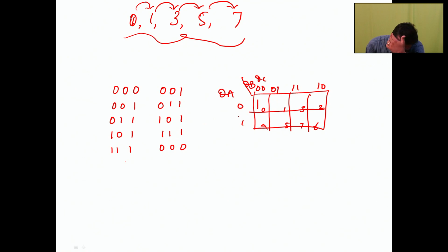They have given these outputs. For all the other conditions they have not given anything, so 2 will be don't care, 4 will be don't care, 6 will be don't care. All the others, the outputs will be determined. Like that we are going to solve the K map, as well as for designing the circuits, where we are going to follow certain rules.